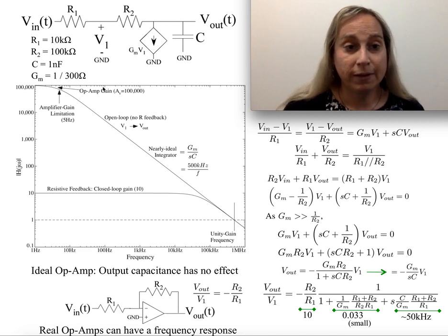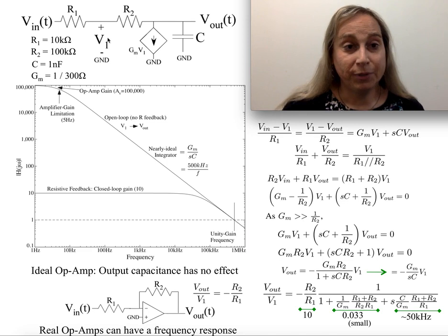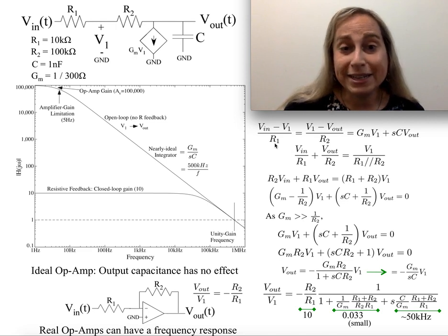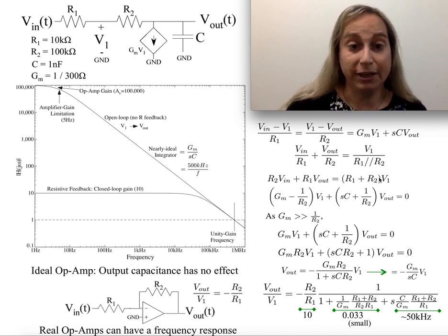So if I wanted to solve this, in this case the simplest thing is to do KCL at one node, or two nodes. I pretty much have this node here at V1 and this node here at V out. That basically gives me this core equation. Looking at the first one, I can do some simplifications, which gives me a typical relationship between V in, V out, and V1. So that works out pretty smoothly.